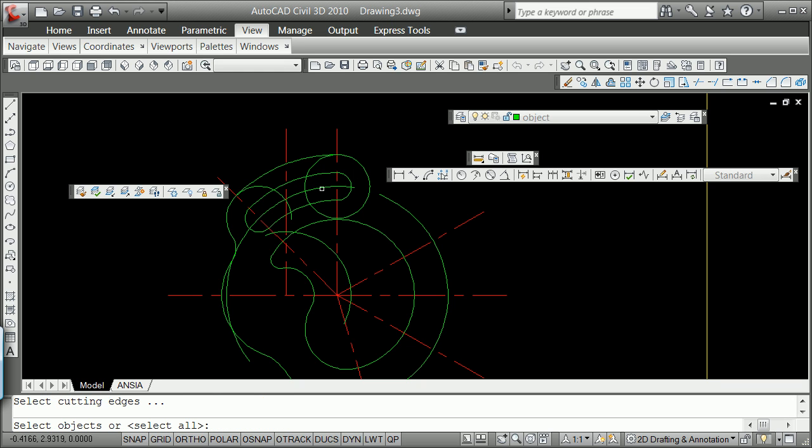Trim out. I guess we don't need to trim. We're going to break around here. Positive direction, fillet radius 0.63. Again, all unmarked radii are 0.63. Once you have that, we can trim this one here. Remember, that was cotangent.